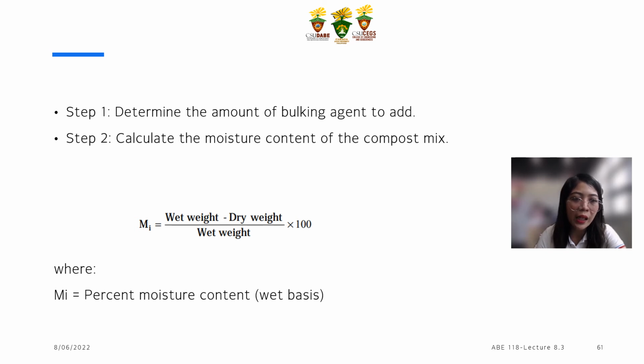So a small field trial is the best method to determine if the amount of bulking agent is required. So, for example, use only a small amount of what you will use before you scale up. To do this, a small amount of raw waste should be weighed and incremental quantities of bulking agent added and mixed until the mix has the structure and porosity desired. So wood chips, bark, and shredded rice are examples of commonly used bulking agents.